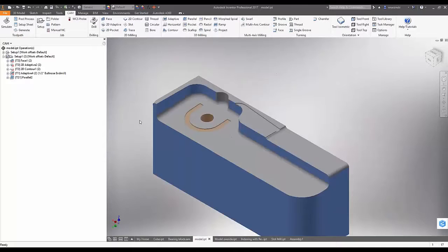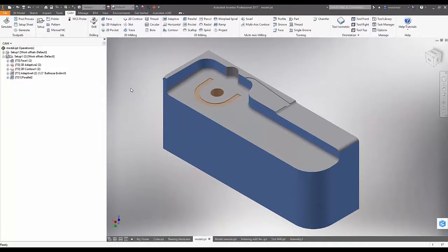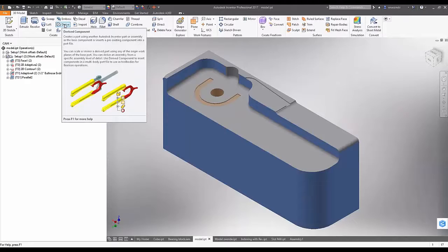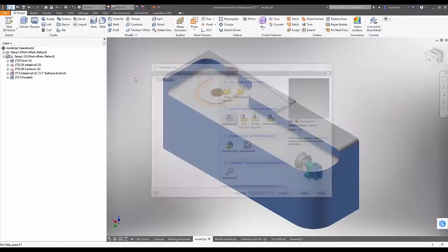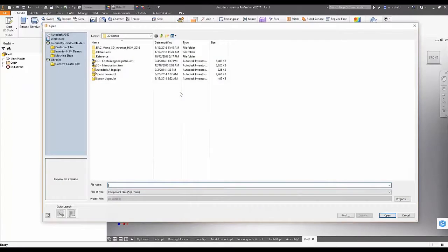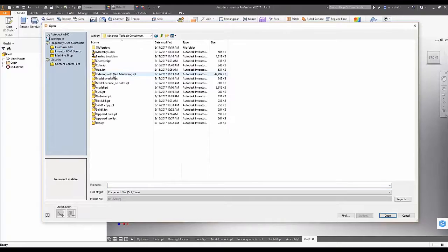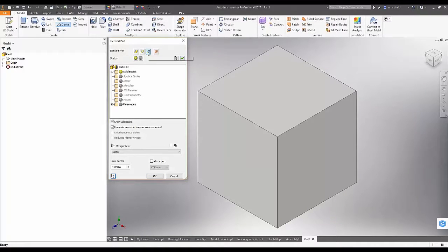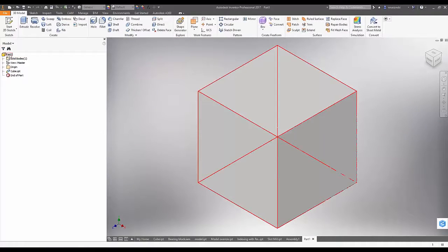That's a great point. Actually, one of my favorite things about that with Inventor and Fusion, I guess you can make a copy of the model, but Inventor, we have the derived component function. And basically, if you start a blank file and go straight to derive, I can come back and pick, let's just use a cube, for instance, that I started this webinar with. And this is the option you want here, is maintain each solid as a body. That basically starts a new part file that is referencing the original.